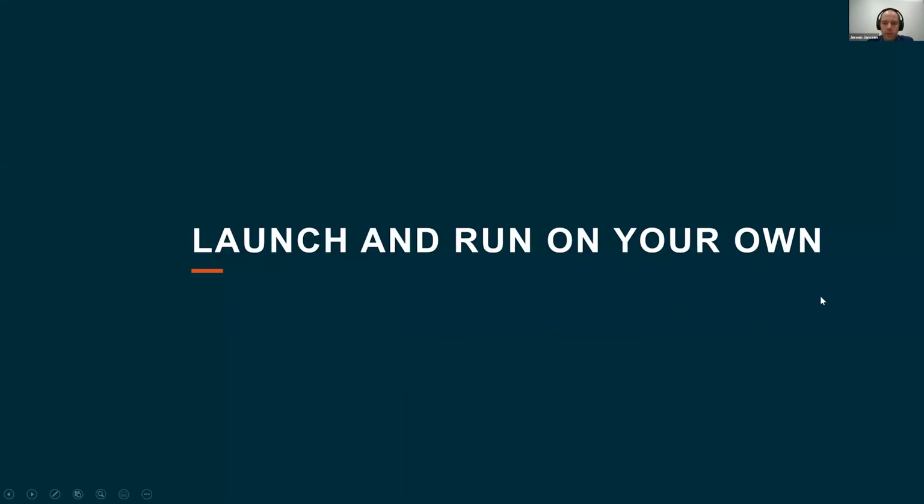Right, so that's the background. Tim is asking, besides geometry cleaning type, are there computational accuracy benefits of SimScale over BlueCFD? Yes and no, I would say. So the nice thing with SimScale again is it's highly automated, and they serve multiple businesses, but a big chunk is the AEC. So they've made it quite easy to run. It's a transient solver, so you actually have fluctuating wind.